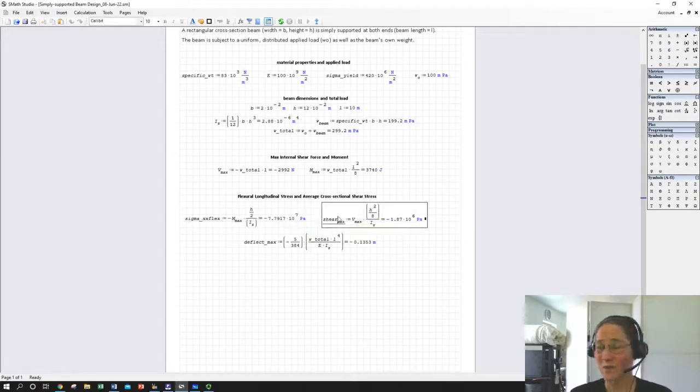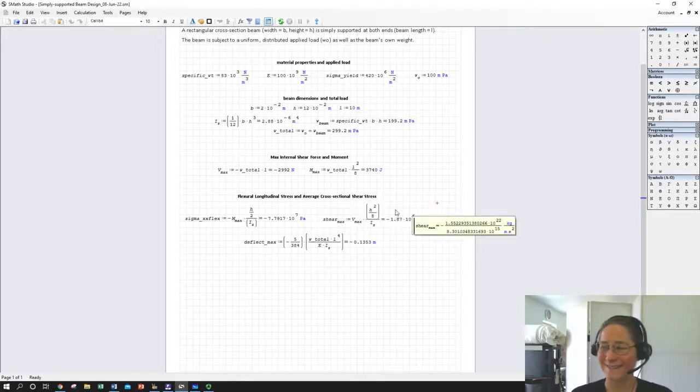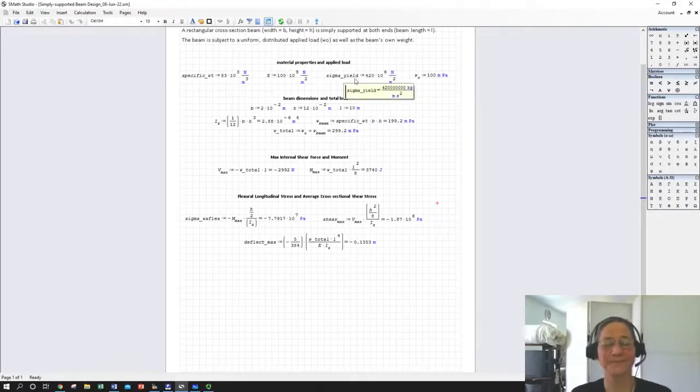For shear, of course, we would compare the equivalent shear stress for this tensile stress, so we'd have to knock that down by a factor of 2 to get the equivalent shear. We'd have to basically do our uniaxial Mohr circle and then knock it down again for our safety factor and then compare that to shear max. So this is a bit of a rosier face than we'd want to see. We have to apply, this is sigma tensile yield, we'd need shear yield. And then deflection would be an absolute value specified by the design. You know, how much do we want the beam middle to sag.